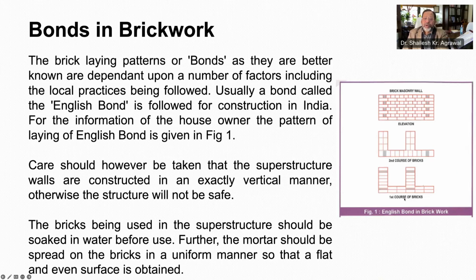The English bond comprises alternate layers of bricks laid as header and stretcher, and this is shown in the bottom-most picture of this figure.